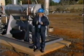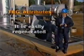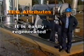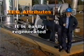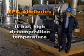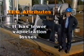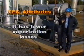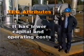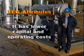Now, TEG is preferred in dehydration units because it is easily regenerated due to its high boiling point and other physical properties. It has a high decomposition temperature of 404 degrees Fahrenheit. It has lower vaporization losses than other glycols, and it has lower capital and operating costs than other glycol systems.